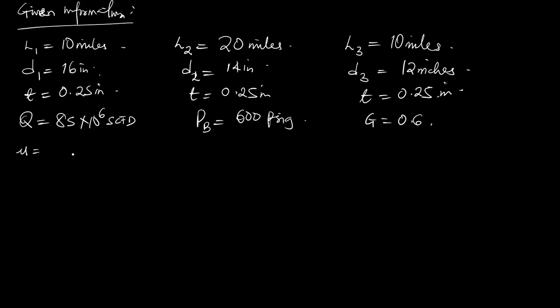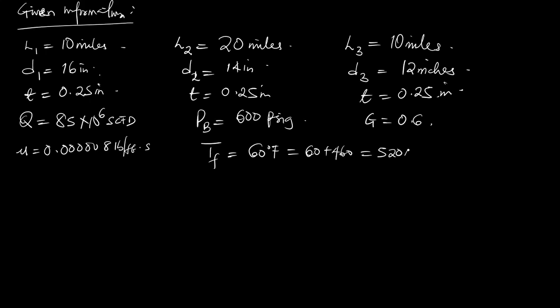The viscosity of the gas is 0.000008 pounds per foot-second. The gas temperature is 60 degrees Fahrenheit, which is 60 plus 460, which is 520 Rankine.